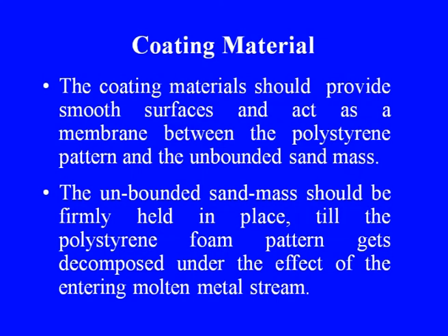The coating materials should provide smooth surfaces and act as a membrane between the polystyrene pattern and the unbounded sand mass. The unbounded sand mass should be firmly held in place till the polystyrene foam pattern gets decomposed under the effect of the entering molten metal stream.